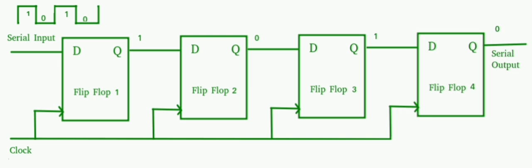Analog output voltage of an n-bit straight binary DAC: V0 equals K times [2^(n−1) b(n−1) + 2^(n−2) b(n−2) + and so on + 2^2 b2 + 2^1 b1 + b0], where K is the proportionality constant, and bn is 1 if the nth bit of the digital input is 1, and 0 if the nth bit of the digital input is 0.